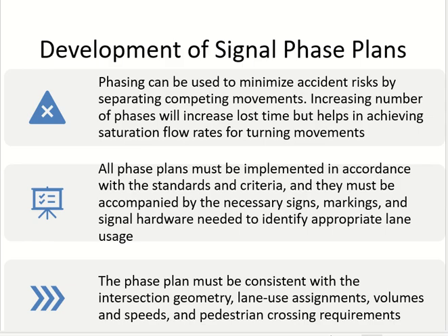Okay. So the first step was developing the phasing plan. In developing the phasing plan, the first and foremost thing is we are putting the signal to avoid conflicts, to avoid crashing into each other. So the first rule of the phasing plan is when you are combining the movements, you cannot combine conflicting movements. Simple. Clear? Logical.